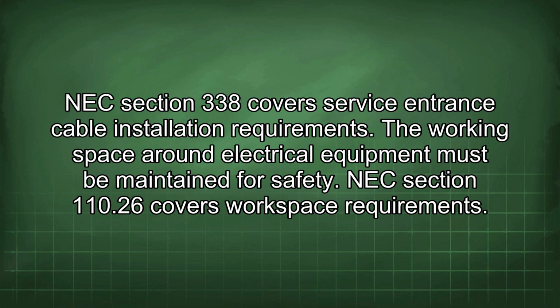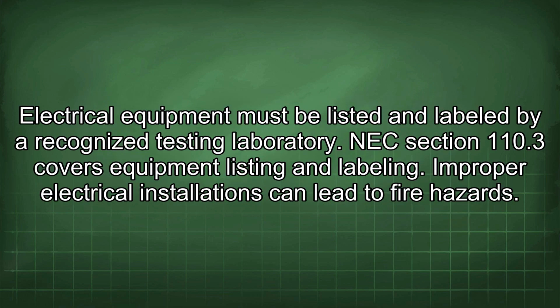The working space around electrical equipment must be maintained for safety. NEC Section 110.26 covers workspace requirements. Electrical equipment must be listed and labeled by a recognized testing laboratory. NEC Section 110.3 covers equipment listing and labeling.